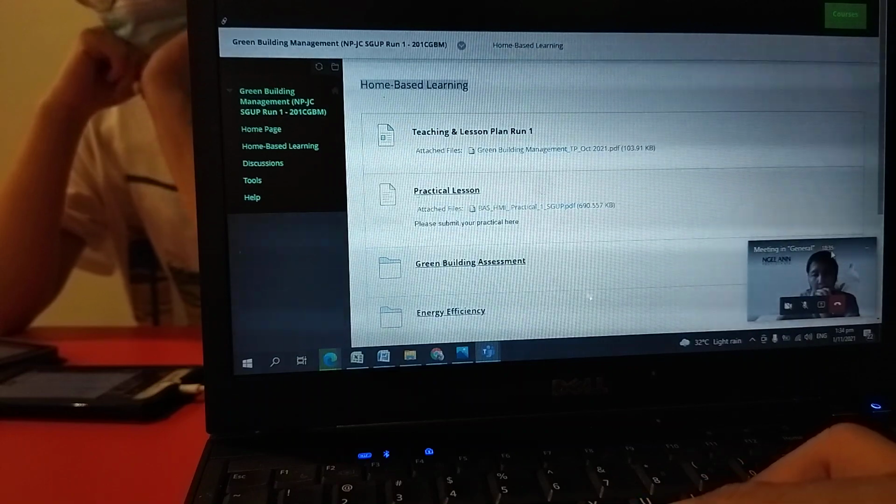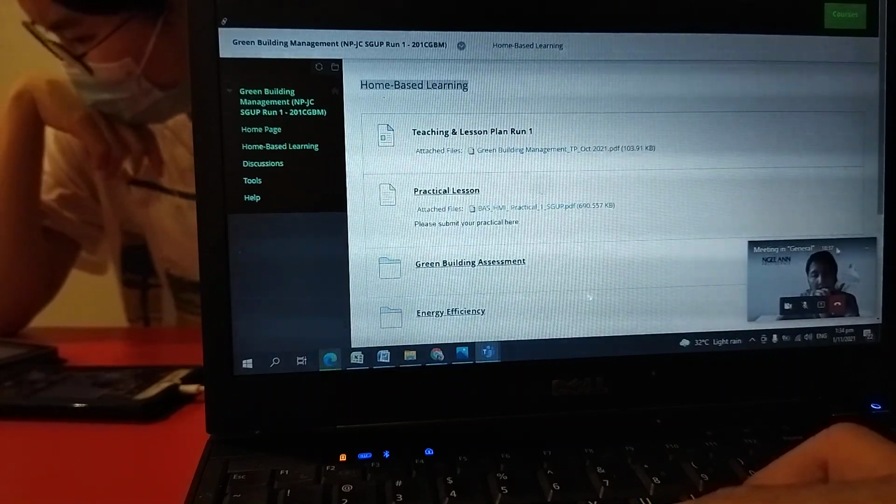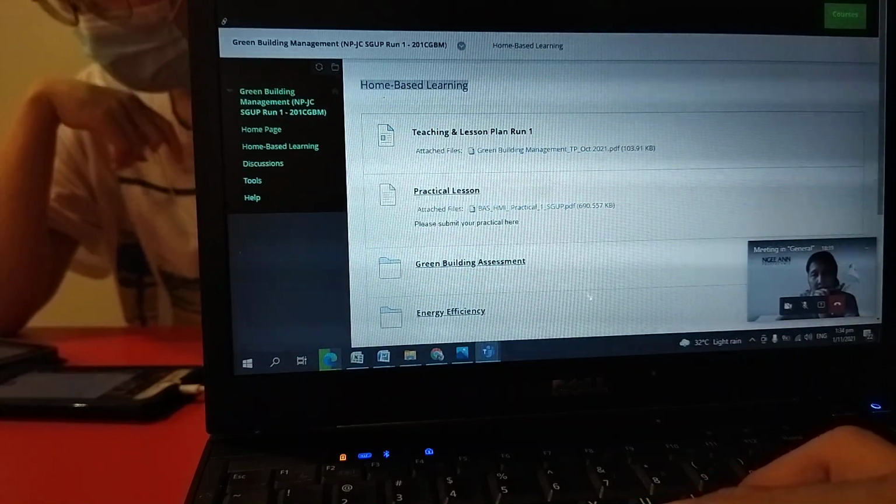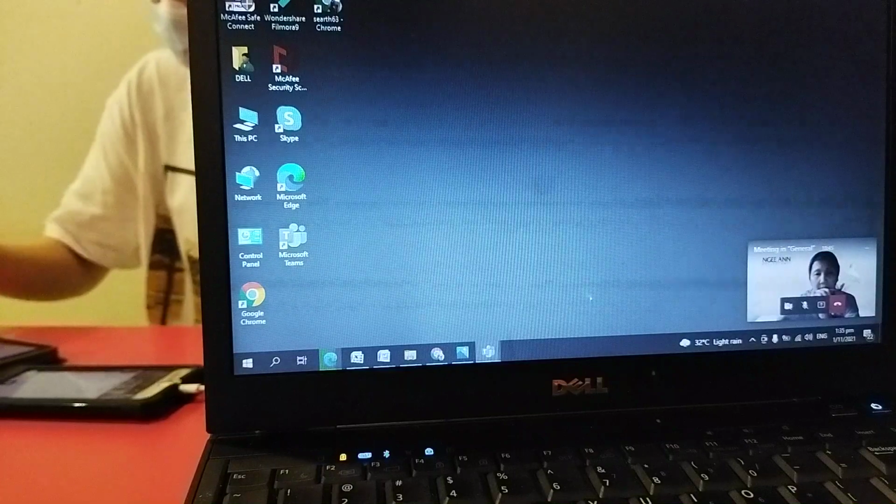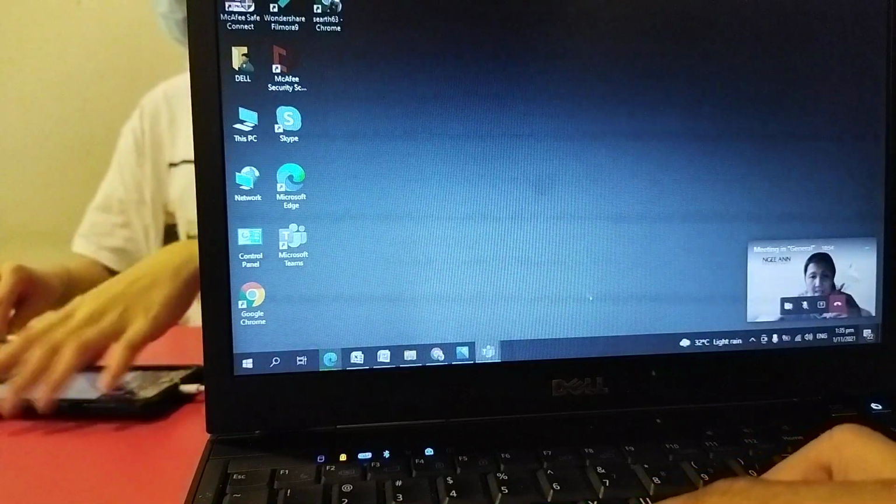So therefore, you don't take advantage of the VSD drive for energy saving. The balance of water will then flow in here, so the flow will be constant all the time. So your consumption of energy will be high, because your pump does not operate on variable speed. Is that clear? Yeah. Okay.